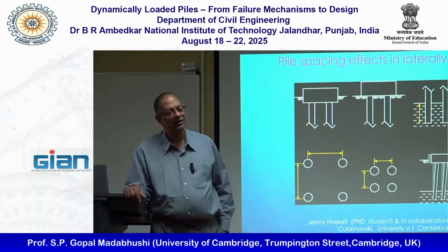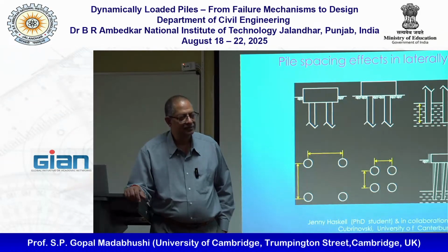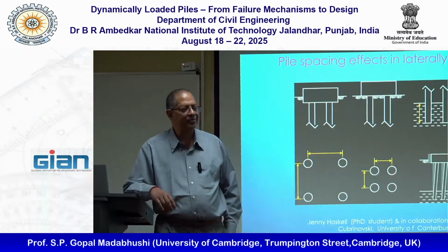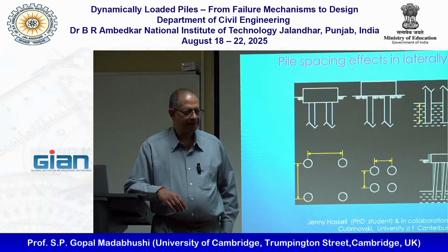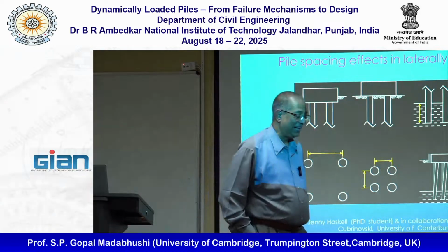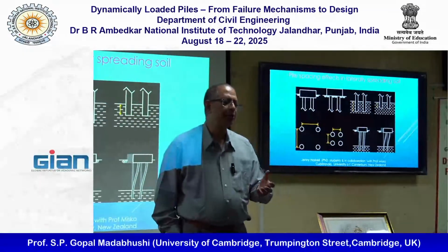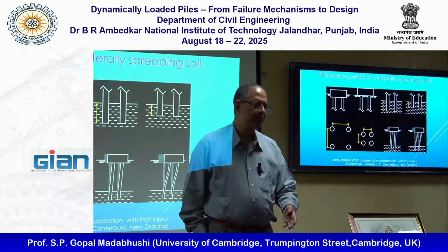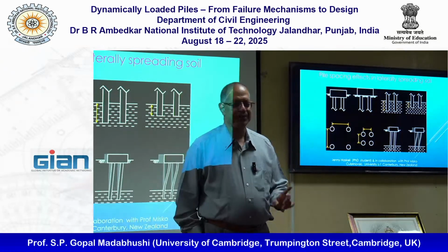Yeah. This is the behavior when the pile cap is resting on ground and we are not considering the pile cap capacity in the design. Normally, you can talk to many designers, they will ignore it. Also, like in pile raft design, we include the capacity of that raft in that way. The behavior will be the same. Now, pile caps are much smaller, and usually you are only using them for maybe 3 by 3 or 2 by 3, that type of pile arrangement, right? To go under the column. Pile raft is a different beast.